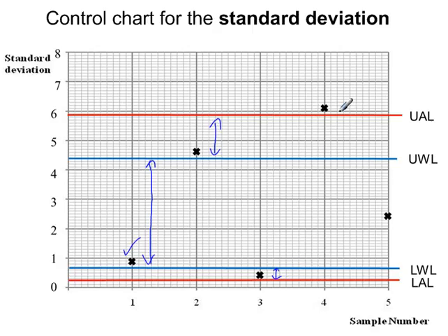This value is above the upper action limit, so we should stop the process immediately and take action. So let's say after this one the process was stopped and changes were made, and this is the next sample taken. It's within our warning limits, everything's working fine.